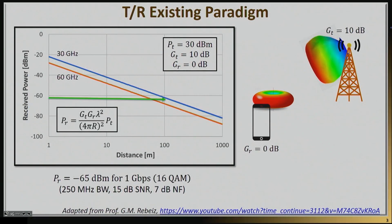I'm assuming that the transmitted power here is basically 1 watt. I'm assuming that the gain of the base station is about 10 dB. I would say that's a pretty reasonable assumption for many base stations out there. And I'm assuming that the gain of the receiver antenna, which is the gain of my cell phone, is about 0 dB. In real life, by the way, receiver antennas in cell phones have gains well below 0 dB. 0 dB actually is a pretty forgiving assumption in that case.